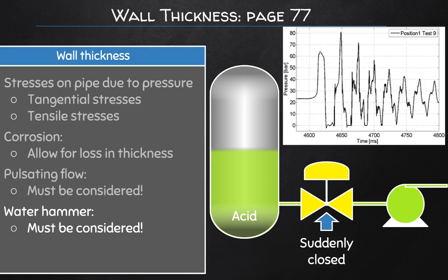another way it will occur, is if a valve suddenly loses power, or a signal is lost, or whatever the reason, and it fails shut. Now, at times we do want such valves to fail in the closed position rather than the open position, so as to prevent a buildup of possible harmful chemicals and prevent any spills on site. So some valves need to fail open, some valves need to fail shut.